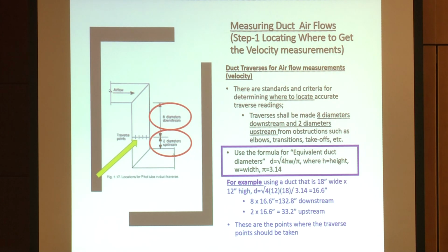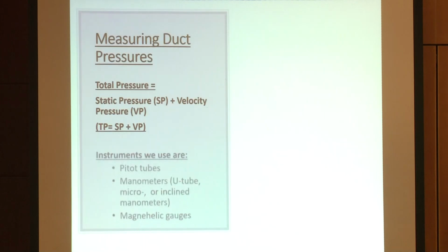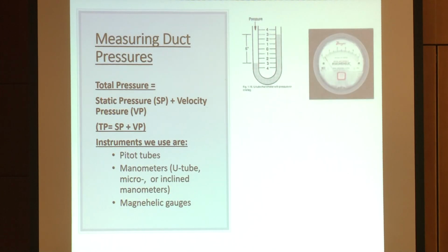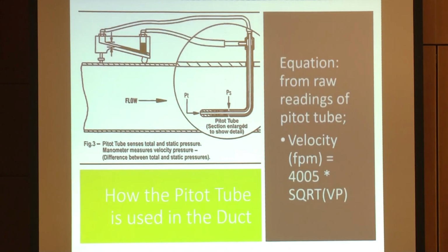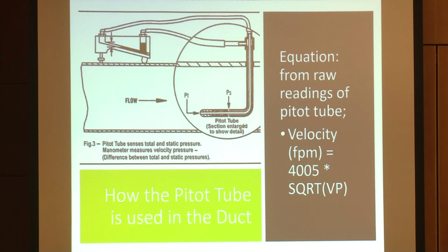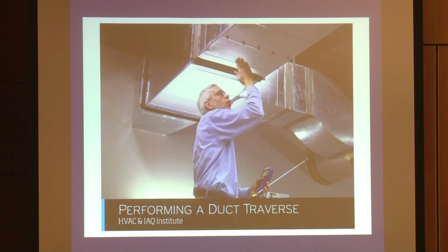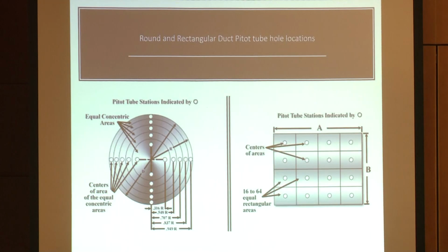You know, pretty much, once you get experience, you can do it very quickly, but still, it's a lot of time and effort on every measurement you make and every measurement you take, and you take a lot of measurements on a job. So now you've got to measure the pressure, right? So now you're going to choose your instrument of choice. Typically, we choose some sort of a pitot tube, and we start looking for what we're going to do.